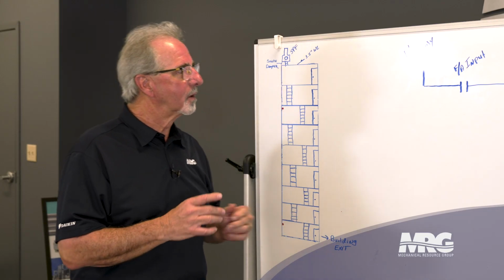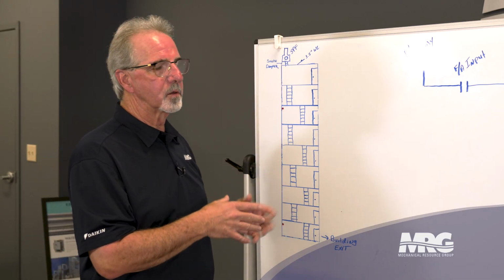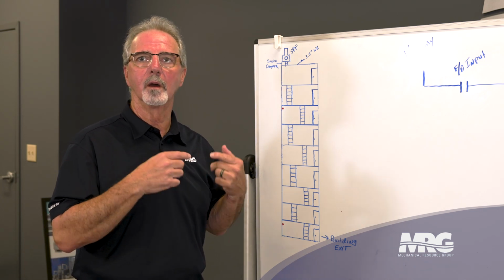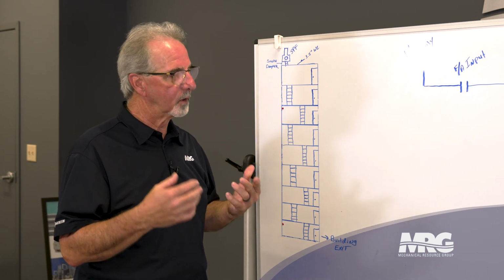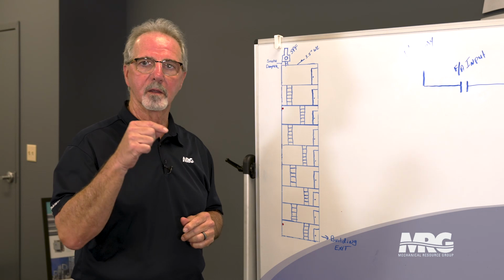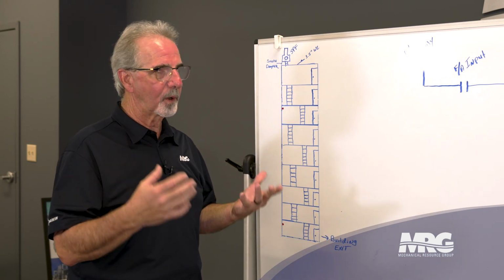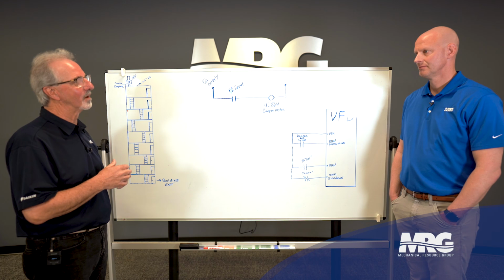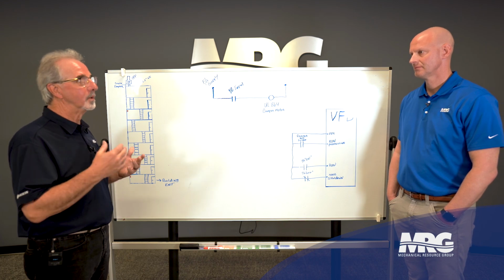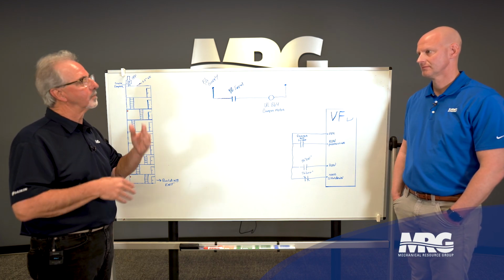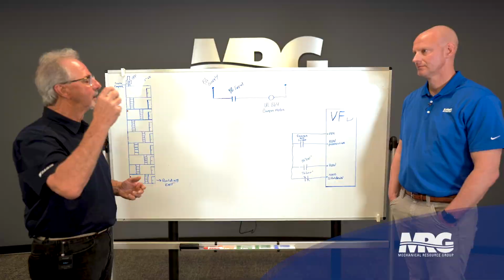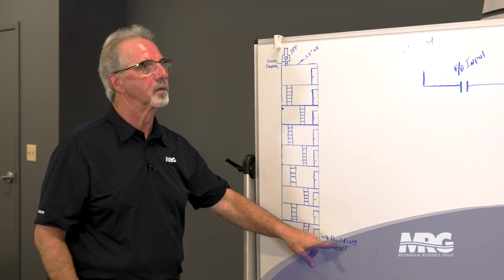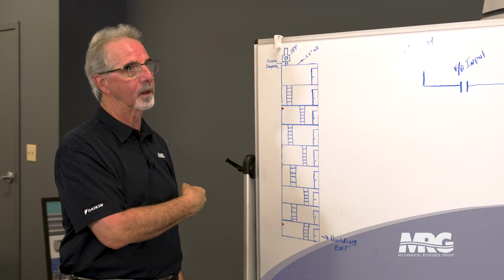The other thing that I wanted to make sure that we covered was the location of these devices. The location of these devices are always going to be on the top floor of a building. If you have a stairwell pressurization fan and it's in the ground floor, probably not per code. Generally, they want these up on top, near the top of the stairwell, because if anybody's going to be running up, they need to be able to get to that. If anybody's running down, most of these exits are building exits. That means once you're out, you can't come back in.